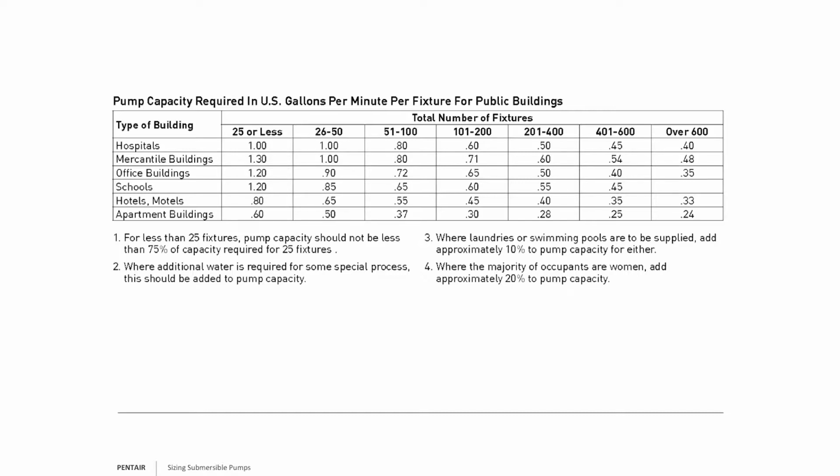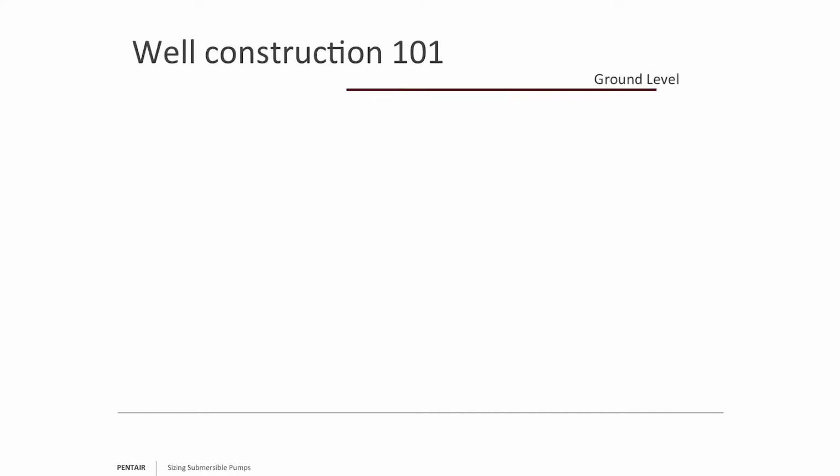My point is simply this. My first starting point is to find out how much water you need. Be it an agricultural project, an apartment, an office building, or a school, we can figure out your usage. Once we have the gallon per minute, the next question is, can the well or the water supply it? If you're limited to a city main, and that city main is 3 inches, and they're only going to give you roughly about 100 gallons per minute, it doesn't matter what your fixture count is at that point. Your limiter is 100 gallons per minute.